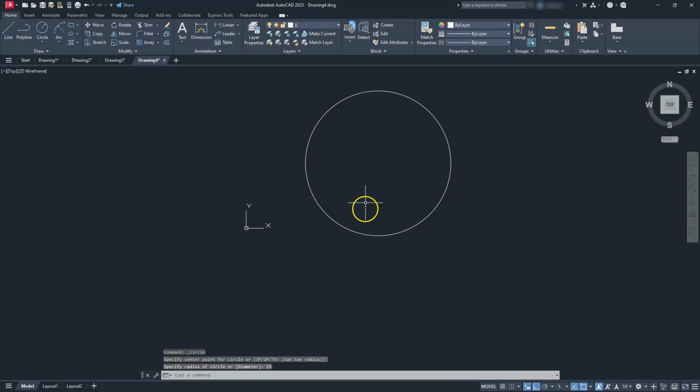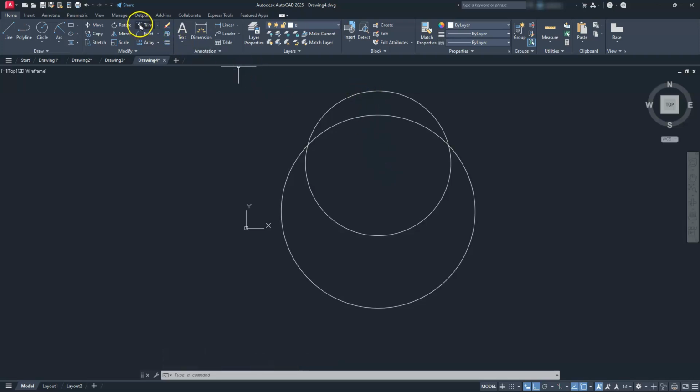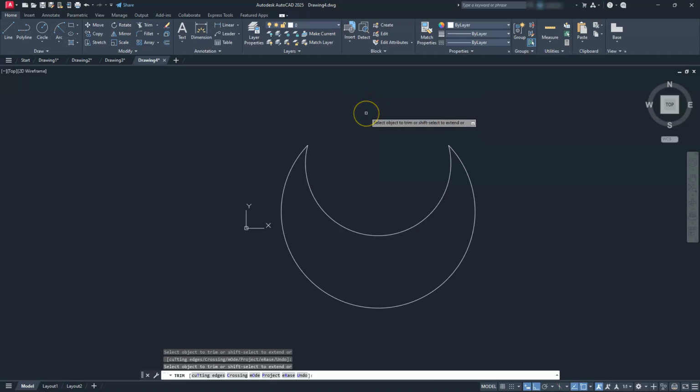Okay. Now I have to create a circle that's located 10 down from this one. So I'm going to go back to circle, center radius. I'm going to find the center of here, and I want you to touch it. And once you touch it, track off of it. Once you've got the green tracking lines and you're facing downward, type in 10, hit enter, and then type in the radius of this one, which will be 20. All right, we have both of those circles drawn. Let's go ahead and do this trimming here, just so we knock out this top part, and I'm just going to trim off these two parts.